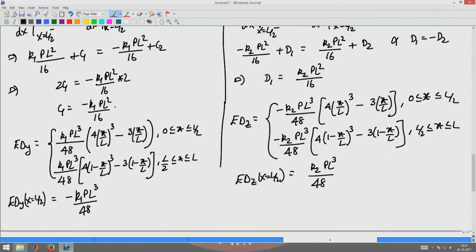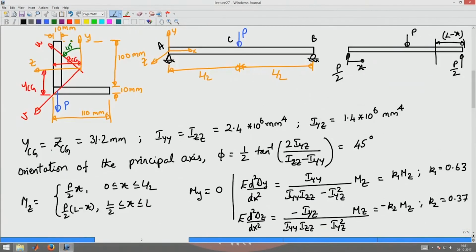Let us interpret this result with respect to the cross section. Okay. Let us go back to the cross section. What deflection we got was negative displacement in y and positive displacement in z, which means the CG from here moves to a point somewhere here, wherein this displacement is the absolute value of delta y, and this displacement is the absolute value of delta z.